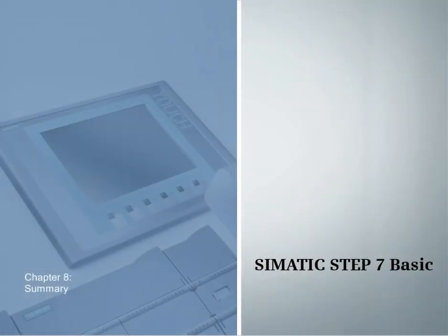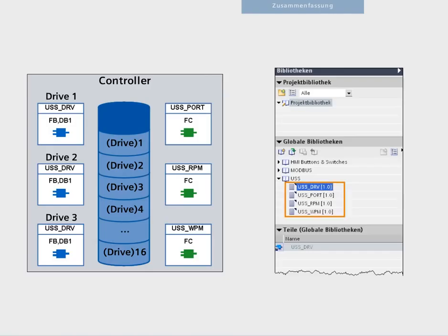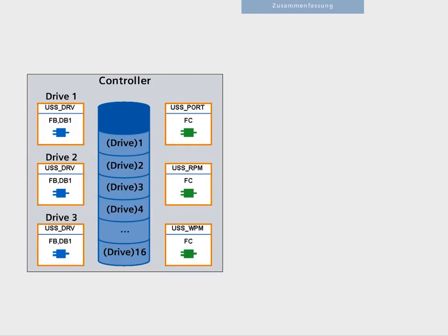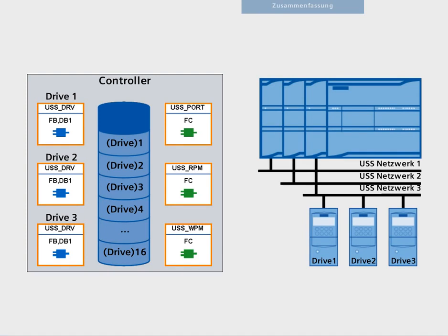Chapter 8, Summary. With the global USS library integrated in Step 7 Basic, it is very easy to program a drive using the Universal Serial Interface, USS, protocol. If you are using 3 communication modules in the S7-1200, up to 48 drives can be operated.